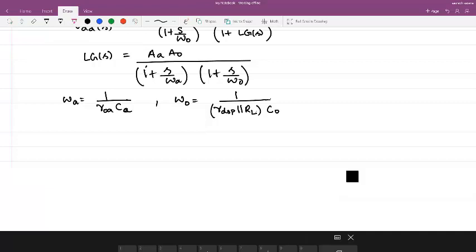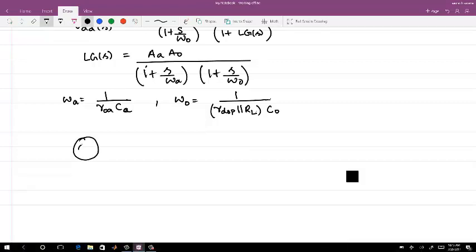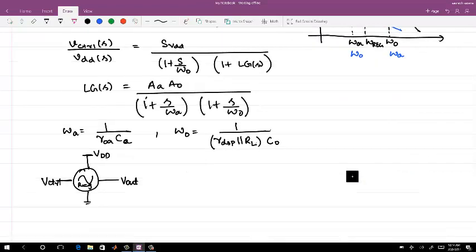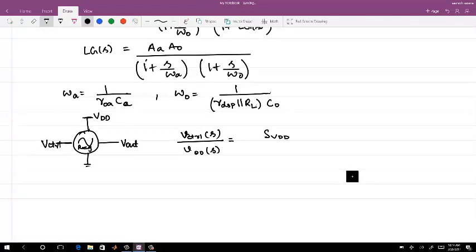to Vout. Now let me say I have ground, VDD, and let's say this is a regulated VCO. I'm writing it here as Vcontrol of the VCO, and this is Vout or Fout, whatever; I should not confuse the terms. Okay, Vout here. So what we have seen is the transfer function from VDD to Vcontrol, which, let me write it again, is sVDD into 1 plus s by omega out times 1 plus loop gain.